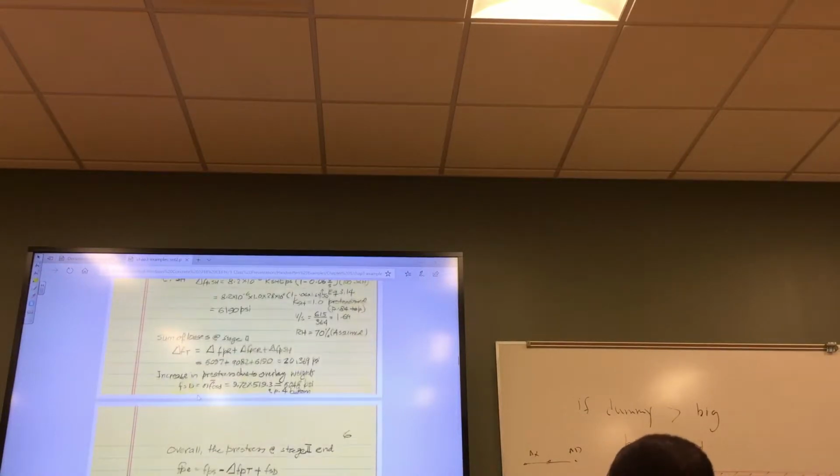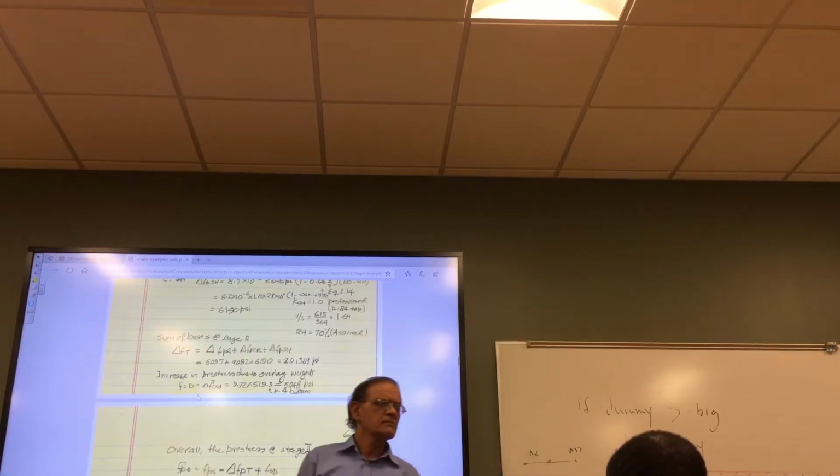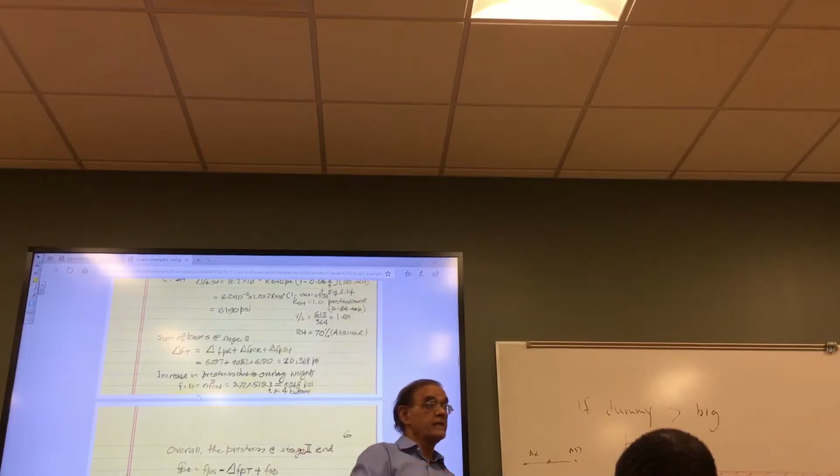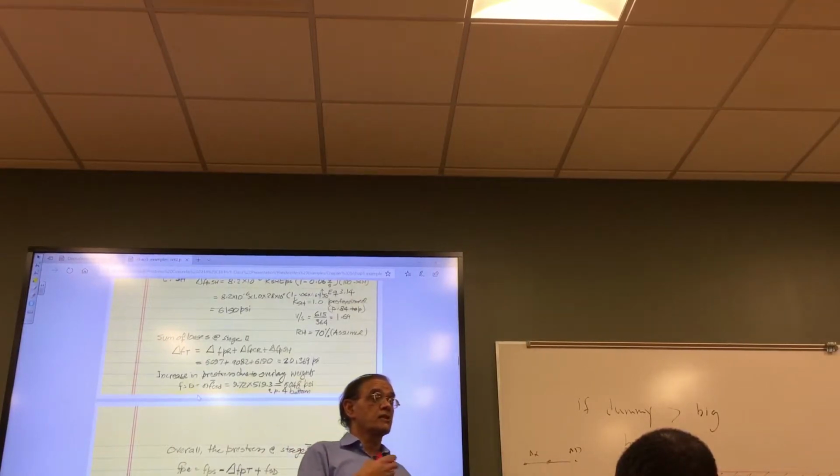When you add the load, because topping is loading, you're loading the elements. By 30 days, we have lost some pre-stress because of relaxation, anchorage, and all that.